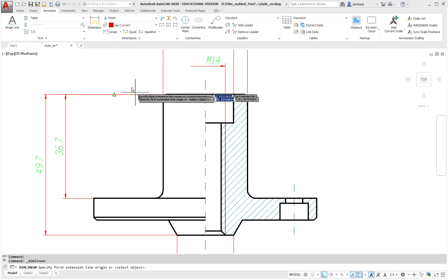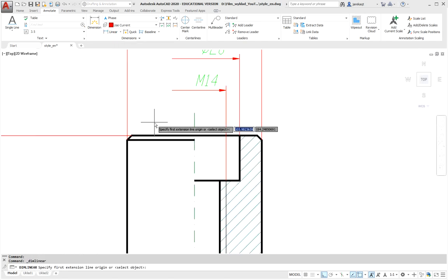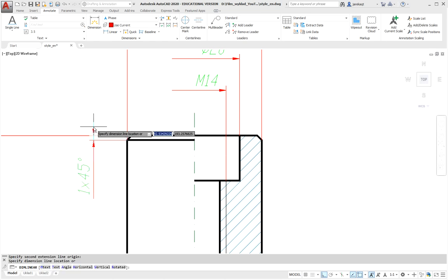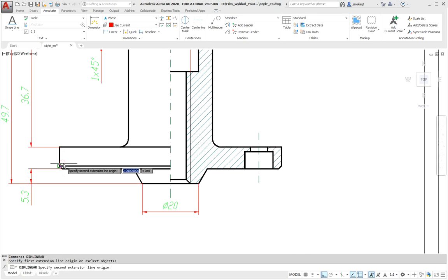Next dimension, now we indicate here and here the polylines and not the dimension, and in height. And this dimension text is placed on the second indication. If it does not fit inside, it is thrown out on the second indication. Now let's move on to chamfer dimensioning. And again linear, and now here the line here and here we can leave at 10. Here, in turn, it's from our own, and we will set it here in half. We will break the rule a bit, but there is nothing blurred. The inscription is legible, so we can give up a little bit of these special requirements.